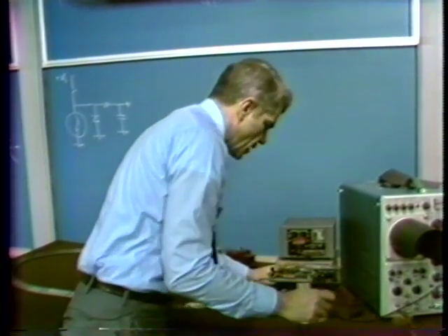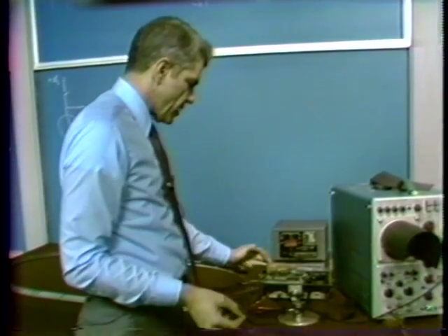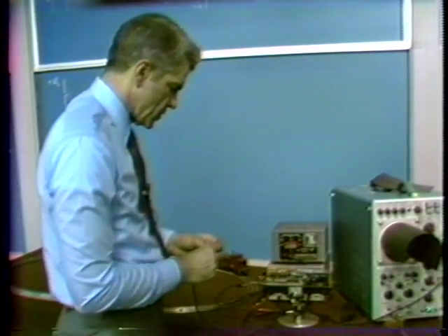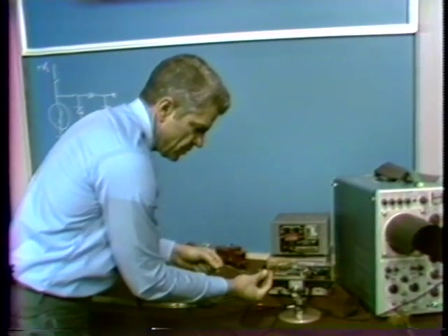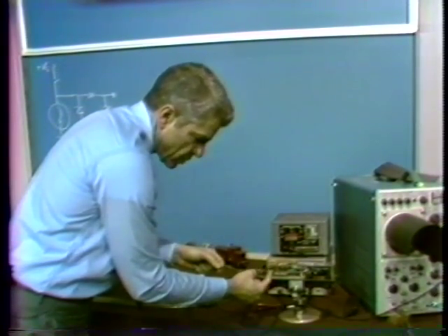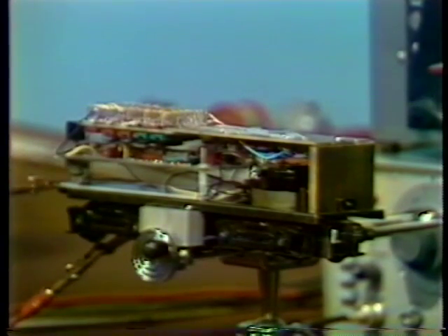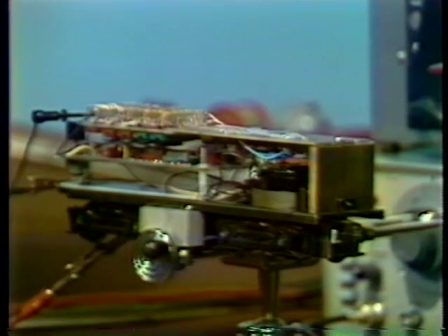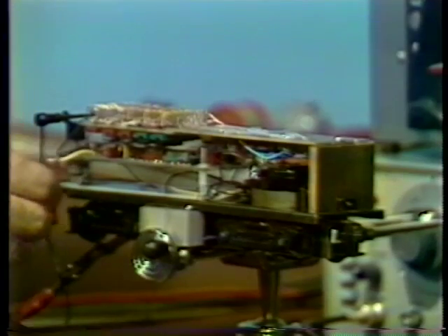And so what I'll do here is take our signal generator with a very low frequency square wave, a square wave at a fraction of a hertz, and I'll apply that to the modulation input on the generator that's commanding the frequency of operation or the speed of operation of my engine. So this gets us a way of modulating the speed.